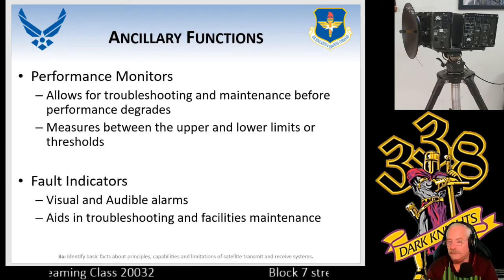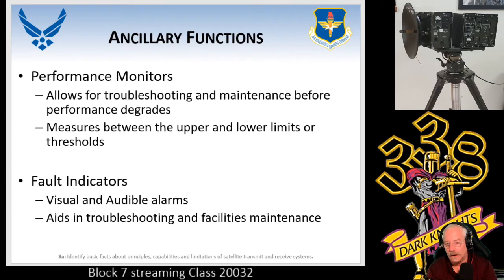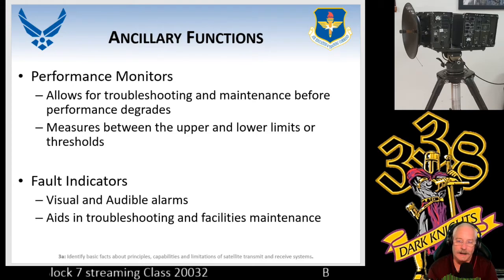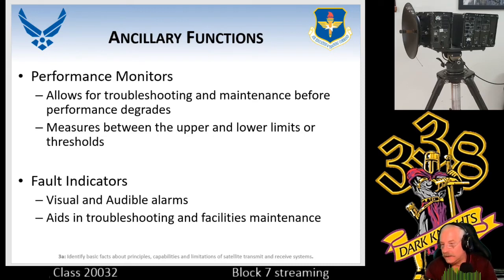Well, when I did troubleshooting back in the day, and I troubleshot a lot of radios, normally I got called out at 2, 3, 4 o'clock in the morning, and I would go to the site, open the door, and never turn on the light. My first thing was to do a visual on all the radios. Why? Well, if all the lights are green and I got one that's red, bingo, there's my visual. Okay, I can see that I've got a problem on that radio. I can identify it. So that's how I troubleshot, and I went from there.